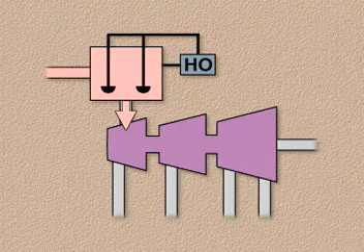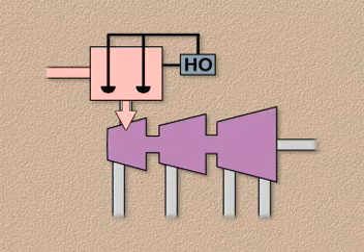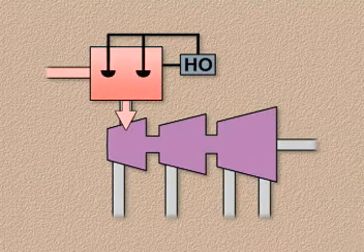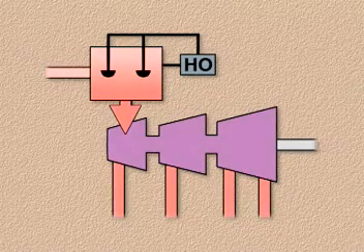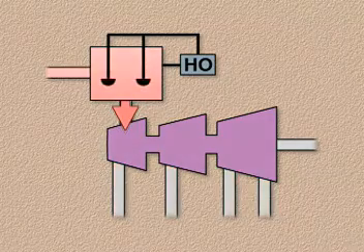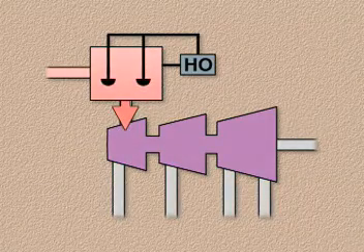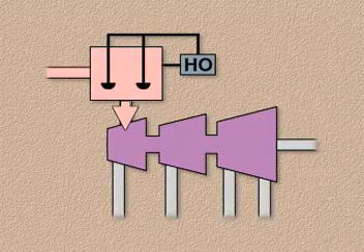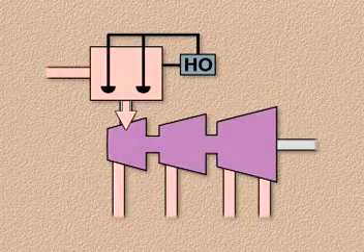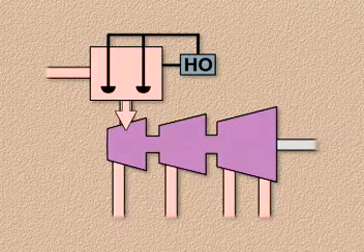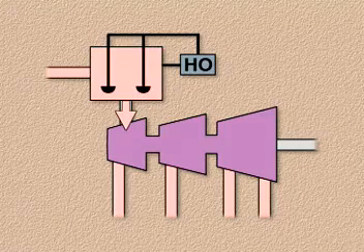The valve positions are changed depending on the desired load. The valves are moved in the open direction so more steam flows into the turbine to increase turbine output. The valves are moved in the closed direction, which reduces the amount of steam that enters the turbine when it's necessary to decrease turbine output. They can also close completely to help protect the turbine from overspeed conditions.